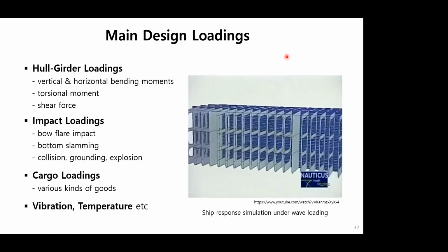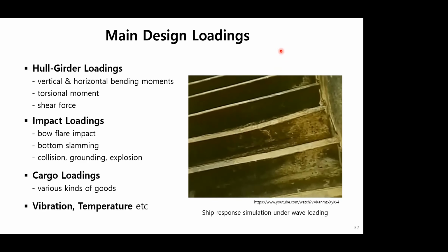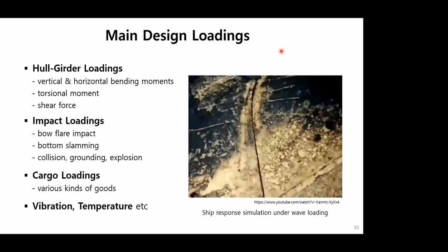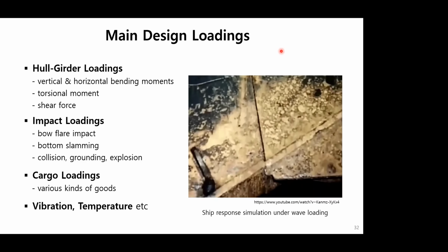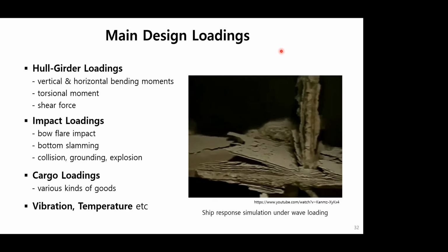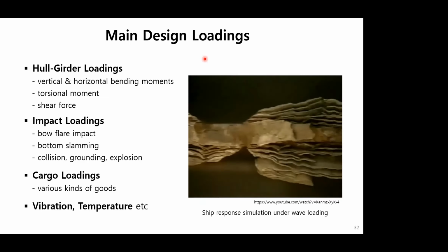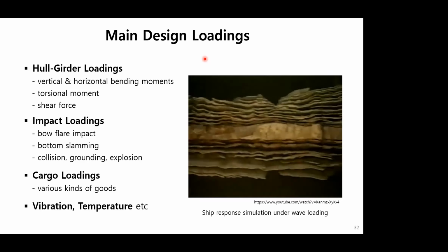Due to the many and variable forces acting upon them, these elements may partly fail and develop cracks and damage in critical areas, causing a serious reduction in local and overall strength. In addition, the aggressive corrosion found when placing steel in the marine environment ruthlessly weakens the steel and its welded connections. This is very useful for our understanding.